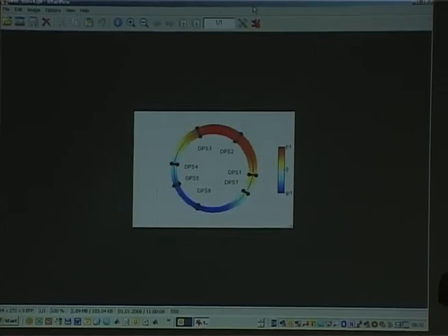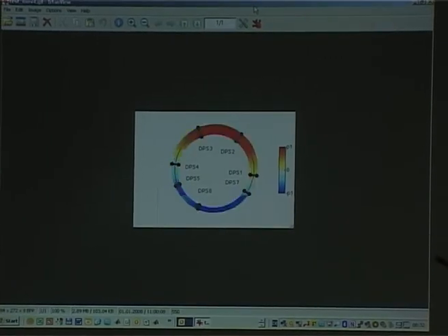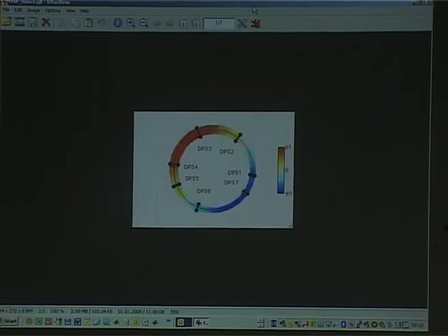And of course this is very important for us to know what's behind this, because here we have the luxury of having 7 probes. In the typical customer engine you only have 1 probe. And with 1 probe, you cannot tell if it is a standing wave or a rotating wave, because you just see a fluctuation. If it's a rotating wave, then at least you know that you get the amplitude right, because it will be kind of uniformly distributed. So no matter where you put the probe, you'll have the same amplitude. If it's a standing wave, you don't know if you get the amplitude right, because if you put the probe on the maximum, you're fine. If you put it on the minimum, it's wrong.